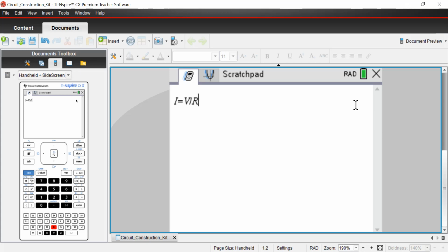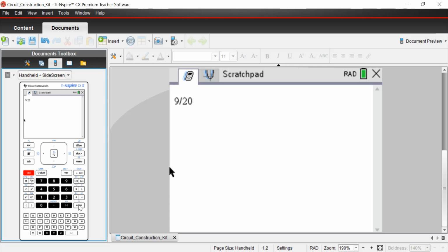So we're going to divide voltage by resistance. When we do that, we say 9 volts divided by 20 ohms, and that's going to give us 0.45. So what happened? Earlier, when we did current, we saw our ammeter read out 0.9. Now we're saying we have 0.45. There seems to be some sort of relationship between current and resistance. So let's take a look at that.